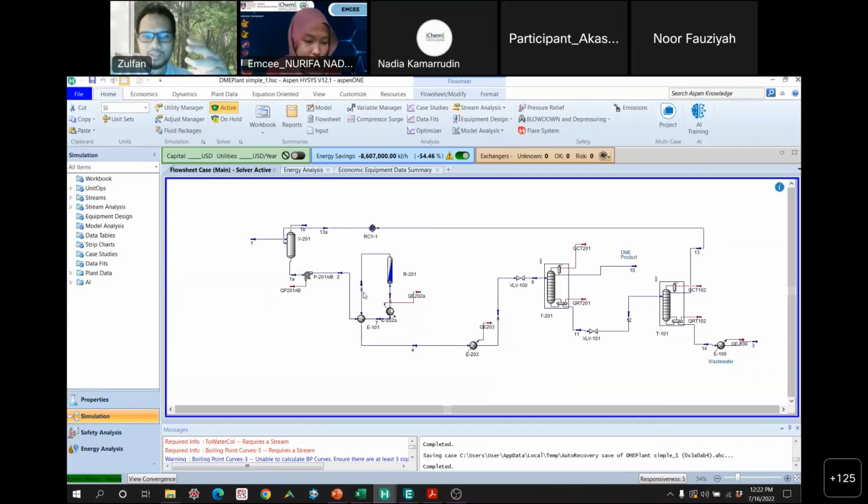So in practice, what they typically do is bypass this exchanger. If they want to maximize the heat recovery, they will just close the bypass and let everything run through this exchanger. But if they want to make some controls, they will open and close the bypass valve in such a way that they can really control. That additional control simply comes from this additional piece of equipment.